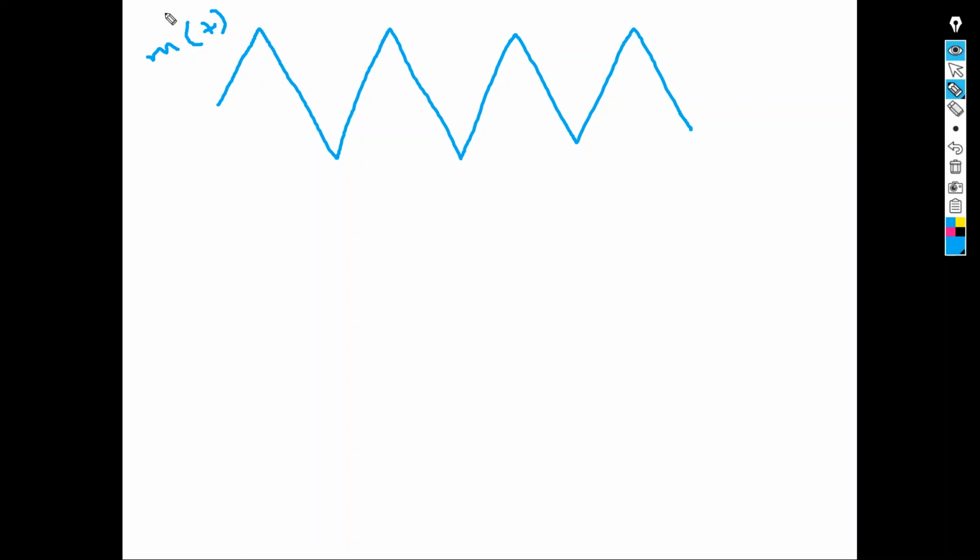What do you do? Since I'm asking phase modulation, you know that with phase or frequency modulation, at the end of the day, the frequency of the carrier will change rapidly based on the information message. Yes? Yes. But I know in phase modulation, the instantaneous frequency changes with the derivative of the message, not with the message directly. True or no? True. Then can I start mapping the message amplitude directly to frequency? No, I need to derive it first.